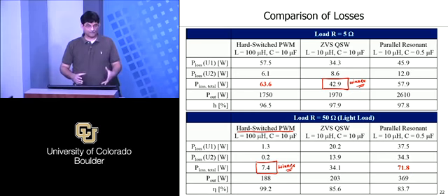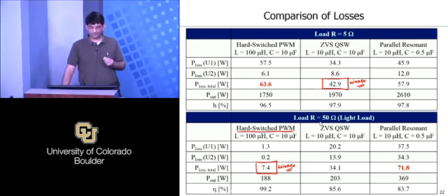But more importantly, it raises a fundamental problem with soft switching converters: you can design a soft switching or a resonant converter really well for one given operating point, but designing it to be highly efficient across a variety of operating points is the biggest challenge. And this course is going to teach you how to do that.